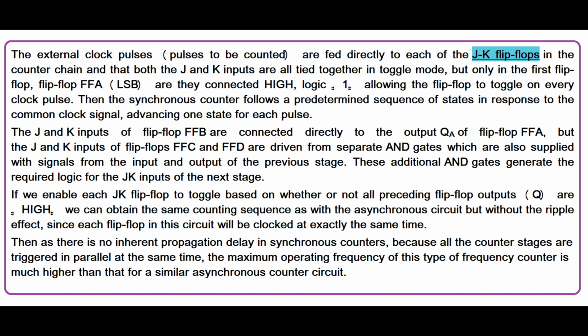FFA, but the J and K inputs of flip-flops FFC and FFD are driven from separate AND gates, which are also supplied with signals from the input and output of the previous stage. These additional AND gates generate the required logic for the JK inputs of the next stage.